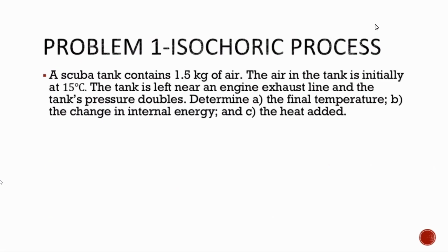Okay, let's have a problem. Let us analyze this first. A scuba tank contains 1.5 kilograms of air. The air in the tank is initially at 15 degrees Celsius. The tank is left near an engine exhaust line and the tank's pressure doubles. Determine A, B, C, and D: the final temperature, the change in internal energy, and the heat added.